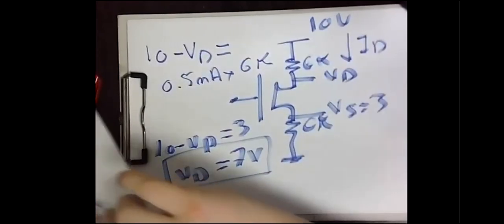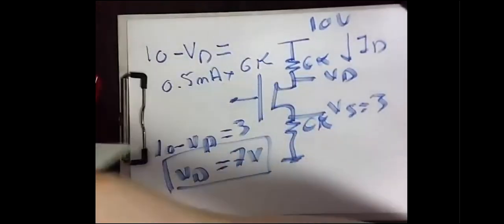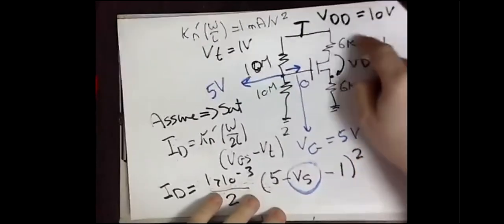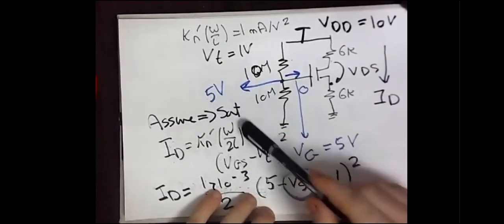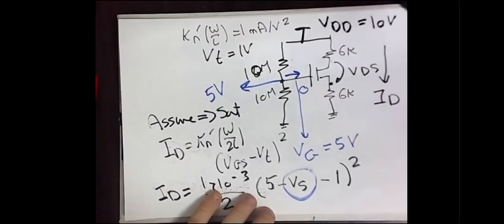Usually, you ask me here. Now let's turn to the first slide. I think yes, this one. Usually, you ask me here, why do you assume that the MOSFET is operating in saturation? Actually, there is no answer for this question. You can assume that this MOSFET is working in the triode region. That's true. And in this case, you will first solve to get the conditions, and you will find that this is a wrong condition. So you will solve it again, assuming that it's saturation.